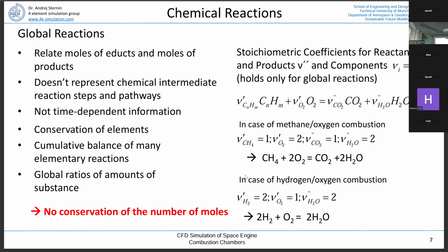So in the boundary layer, we need to cool our combustion chamber, and since we use copper in a rocket engine, we are not able to go to temperatures higher than 900 Kelvin, meaning that in the boundary layer, the gas will be cooled down to 900 Kelvin. And if we look now at reaction times, we will find out that at these low temperatures, some hydrocarbon reactions are not able to reach chemical equilibrium during the residence times.